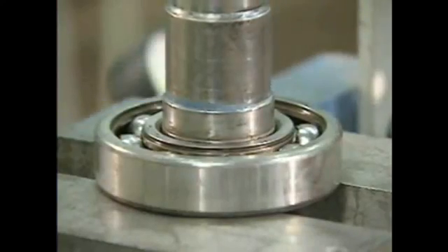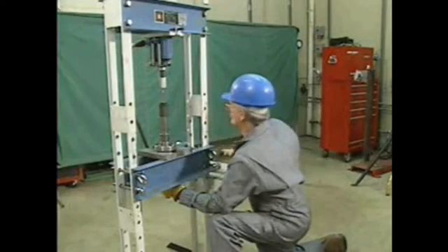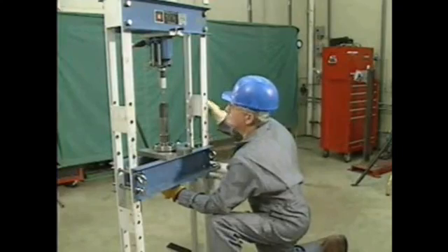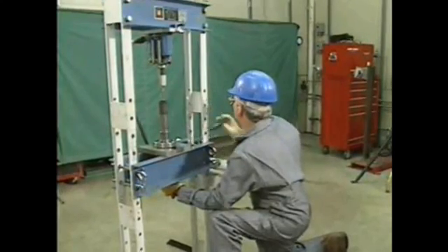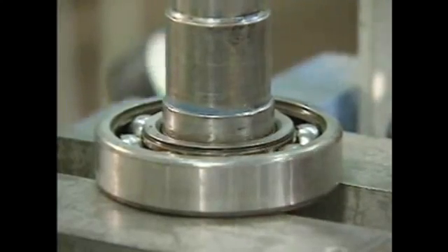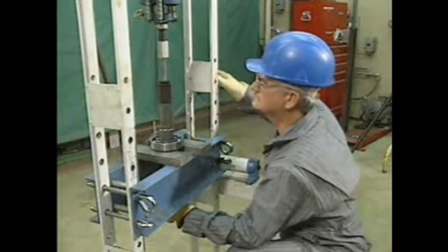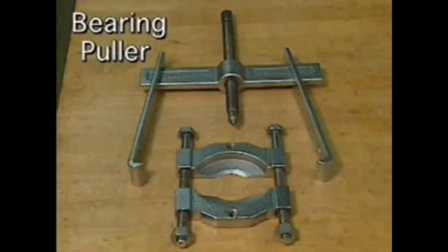As the shaft starts to move through the bearing, he watches the bearing to make sure that it does not jump off its supports and to make sure that it is not cocked. If the bearing is cocked, it will jam on the shaft. As the shaft is forced straight down through the bearing, the mechanic holds onto the shaft with one hand to prevent it from dropping.